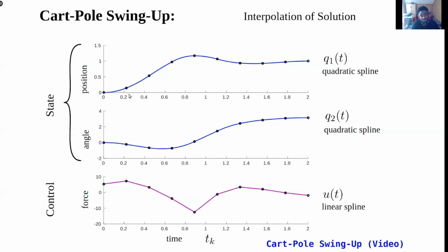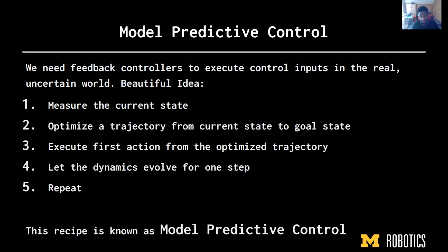But what if we end up in a state that's not along this trajectory? What are we supposed to do? This is going to often be the case because in the real world there's a lot of noise. Even if you're trying to control a vehicle and you give it the control to end up at some state, it's probably going to miss most of the time because of friction in the ground, as well as some other noisy artifacts of the real world.